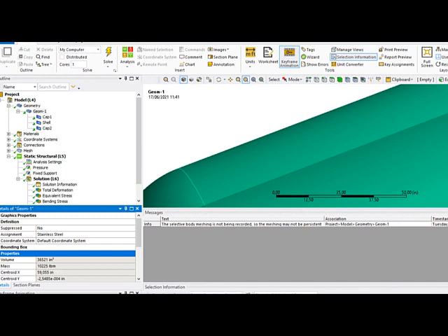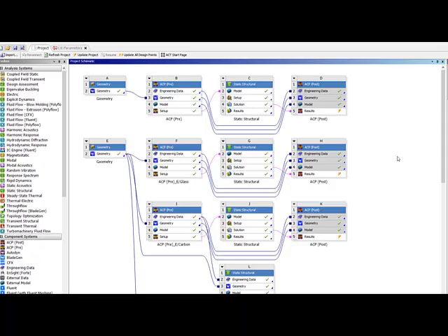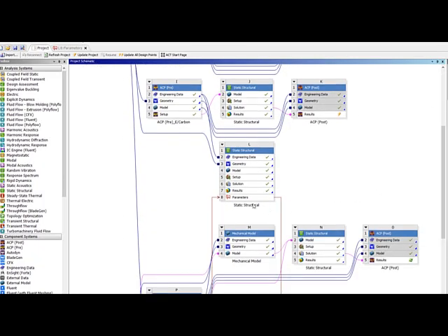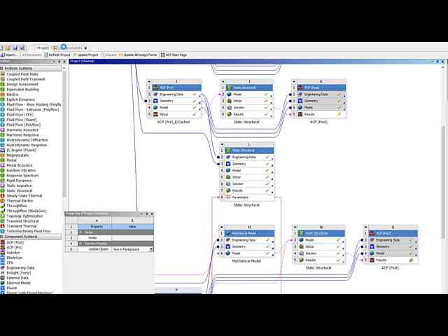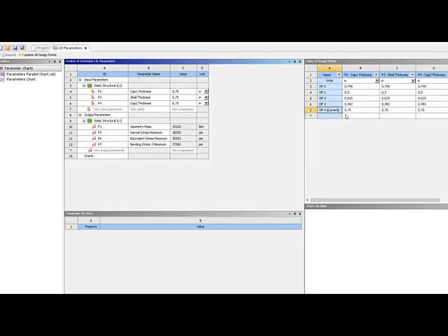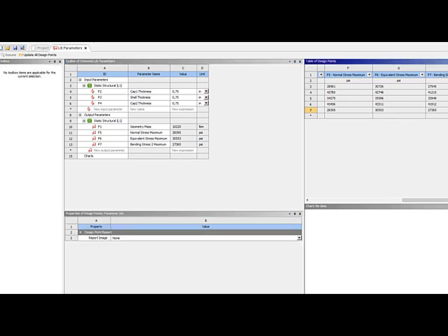If we do a simple parameterization, for example, using some parameters, here we can see how the change in thickness increases the stresses. For example, here the equivalent stress. If we work with 3/4 inch, the stresses, for example, the equivalent and the bending, are of these values, right? Now let's see how it behaves in a composite pressure vessel.